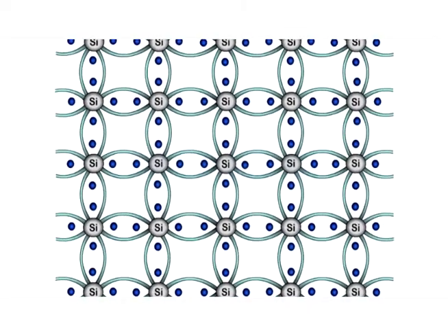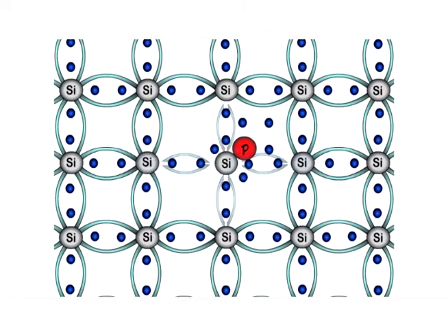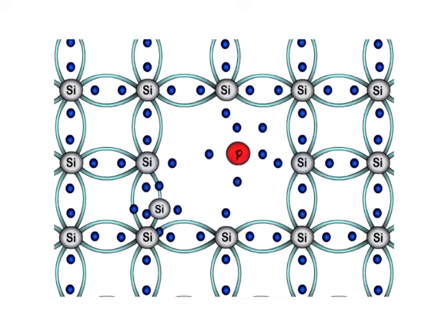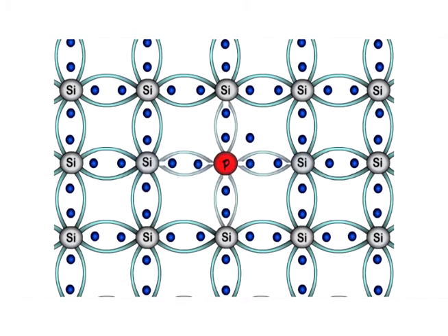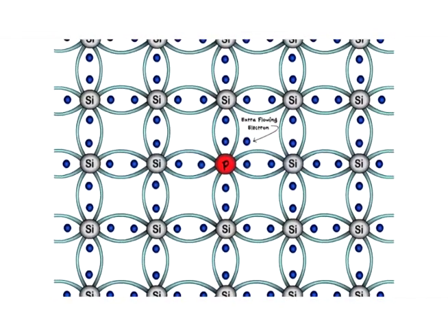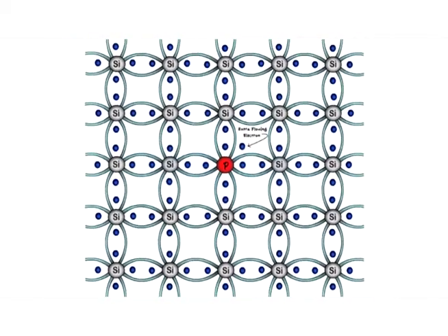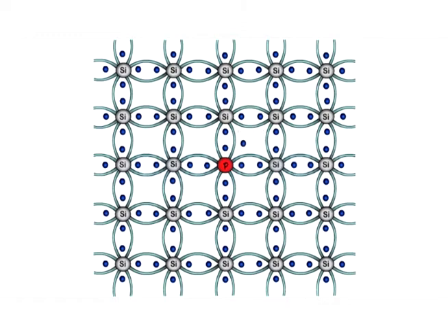When we add a pentavalent impurity to an intrinsic semiconductor, we observe that the phosphorus atom forms 4 covalent bonds with the silicon atom, fulfilling the needs of silicon. But even after that, there remains 1 electron which does not form any bond and remains free. And so, unlike the previous structure, we get a free electron available for conduction. This electron rotates randomly around the phosphorus atom, following a circular motion. In addition to this, the breaking of bonds as seen in intrinsic semiconductors happens here as well.